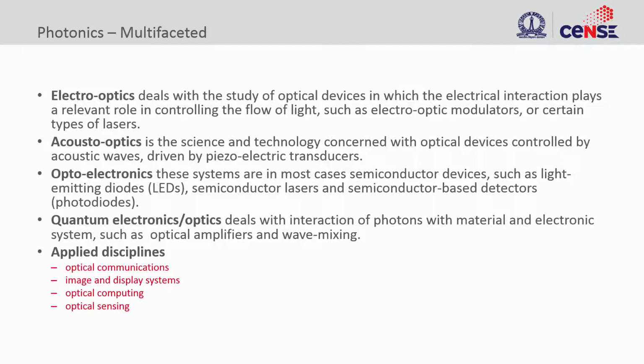And if I can use that to do electro-optics, I can do similar things through acousto-optics. Acousto-optics is nothing but changing the flow of light by using acoustic waves. I can create acoustic waves by using a piezoelectric transducer, for example. So, I can use a piezoelectric material in order to control the flow of light. There is also an interesting way to look at these acoustic waves, through the phonons that you have in the system.